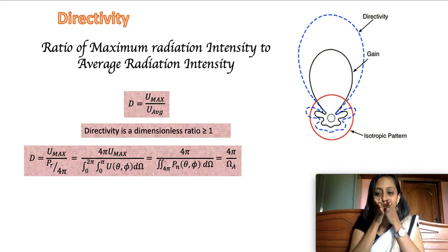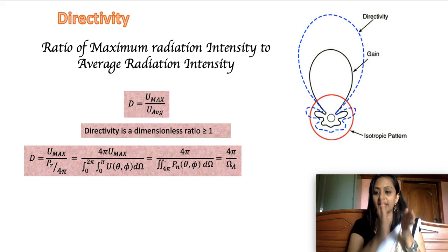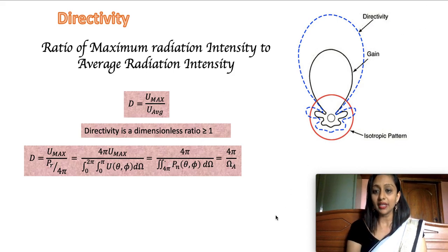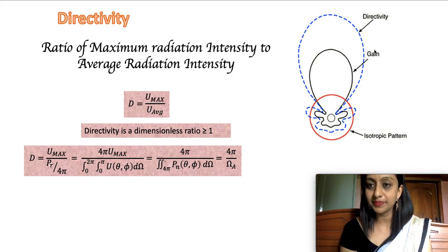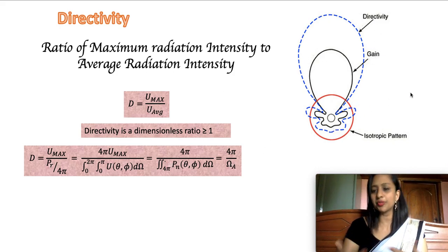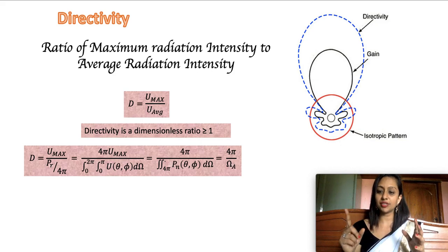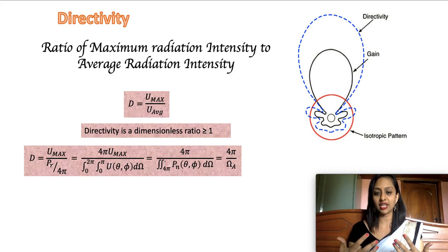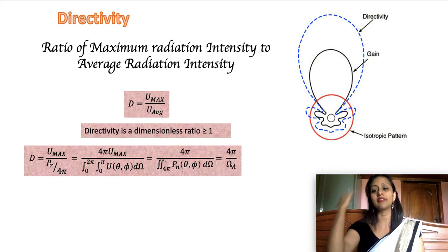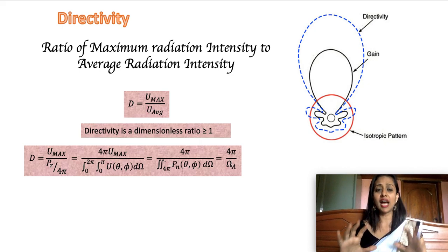If I confine myself and speak in a straight direction with the same pitch, the distance would have increased. Hence, this is my directivity. Okay, so this means the distance would have increased. Yeah. So directivity for an omnidirectional antenna is 1. Any other directional antenna which we design will have a directivity more than 1. Okay, so this is the ideal case.